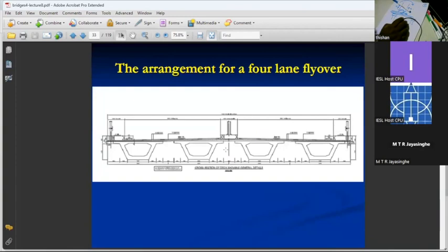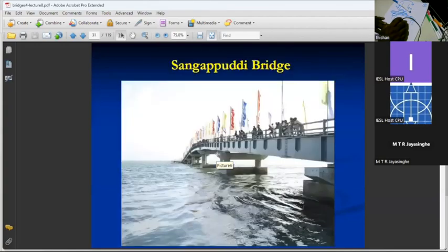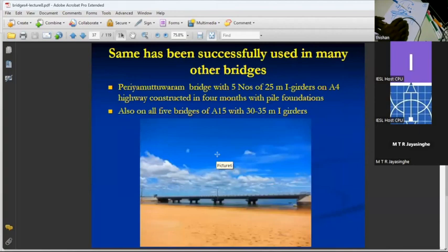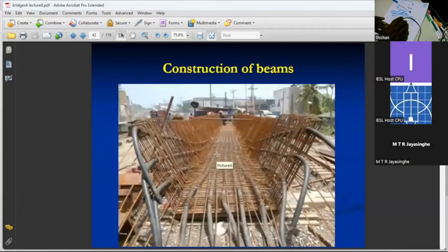These are the kind of beams that we used, and because the original design was a box girder, the box girders of about 1.35 meter depth, even with these beams, we had to match the original depth, because we had to ensure that the profile of the road, highway profile, has been maintained. So we used that, and so I can go further and show you the situation.